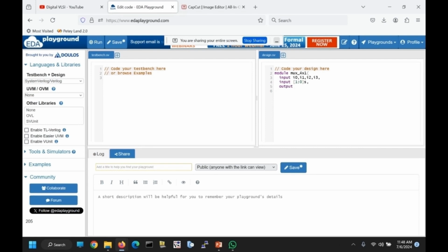Here the output signal is declared as type reg in the module port list because it is used in a procedural block. So output reg Y. Here I am using an always statement followed by a begin end block. An always statement is executed every time its sensitivity list gets triggered. In most cases, input variables are present in the sensitivity list. Another way of expressing this list is by using an asterisk symbol. So always @(*) begin.